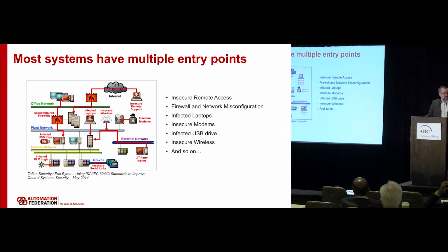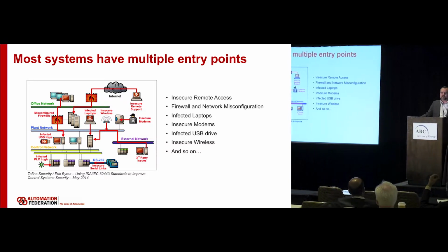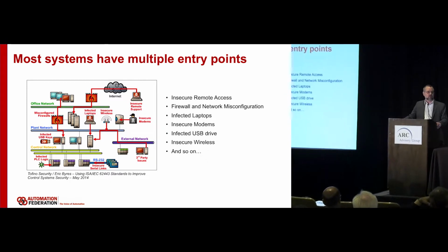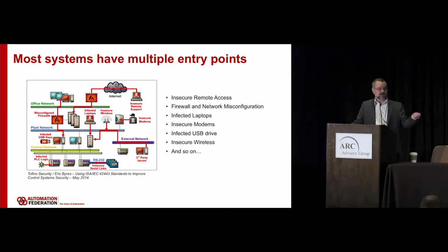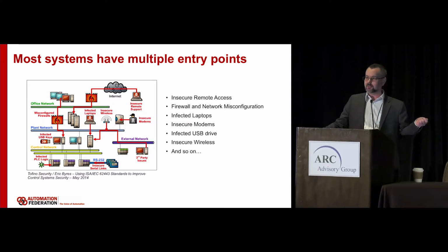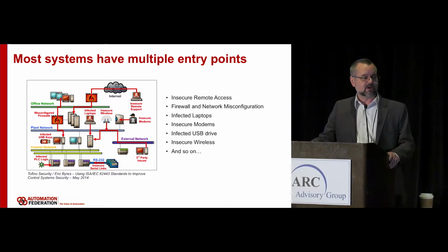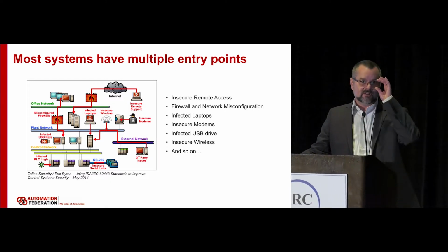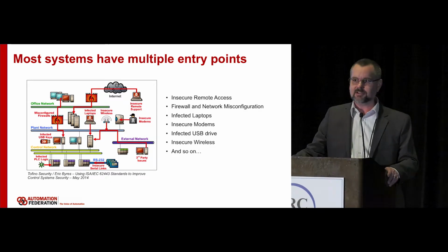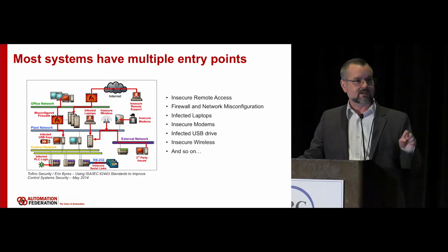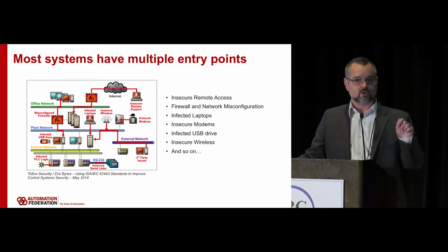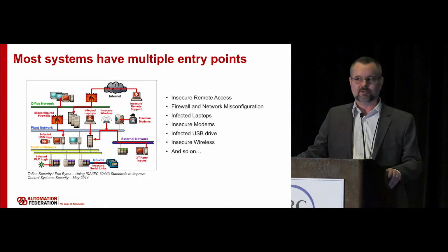And there are many, many different methodologies to get in and out of these systems. Vendor laptops: how many vendors walk in with their configuration device and plug it into your network? Did you scan it beforehand? Is that laptop going through your security policy process? I would tell you that it shouldn't be the vendor laptop, and the vendors will complain about this, but you should give them one of your own that's under your security policies and make them load their software on it. Then you should control that, check it in, check it out, and have a procedure.